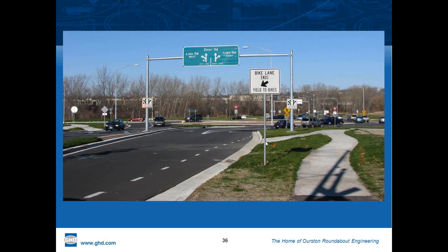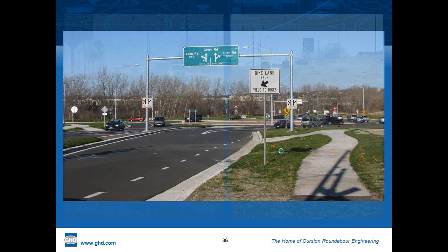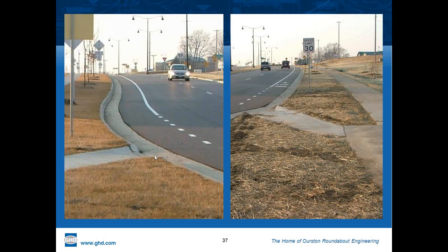And so there's different designs that develop. This one happens to be in Madison, a two-lane roundabout with overhead directional signs combined with regulatory signs, cyclist lane ends, and a good skip line showing the departure point, clear poles and things like that. All those are important considerations for the cycling community. Another design. This one's not as well developed because it's on a curve, and the reentry point on this one isn't as well developed either because the angle into traffic is quite steep.